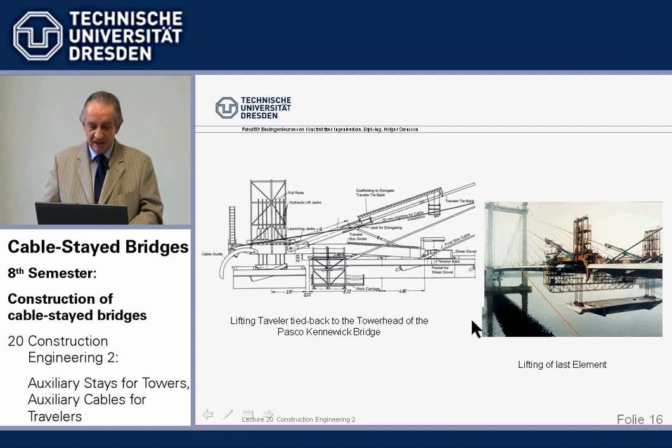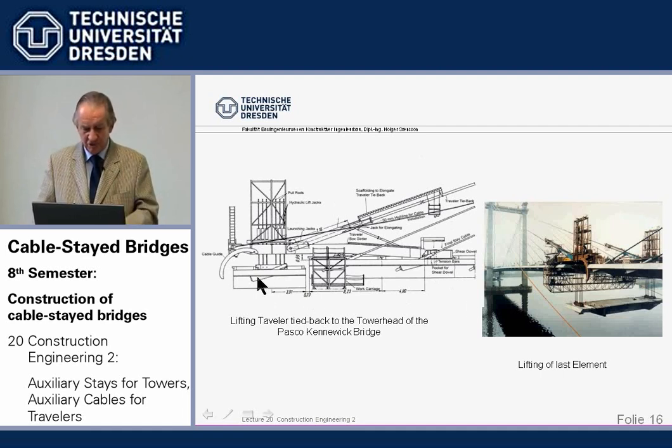And anyway, here we had the 300 ton, was very early, 1976 as I said. We had here the 300 ton precast element, you see it lift up. And then we said, okay, at that time there was nothing in the US, we used a lift slab from buildings hydraulic system. And we had the horizontal backbone of the traveler here, which then was to hang back the traveler into the tower to unload the beam.